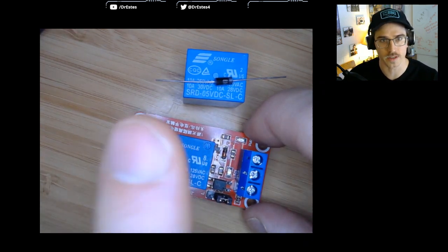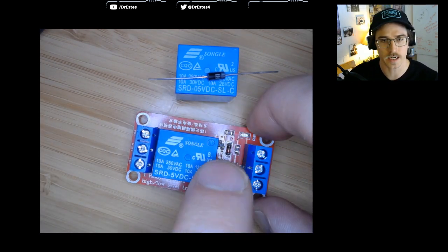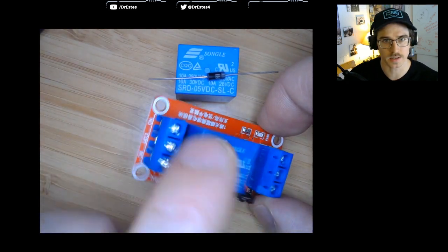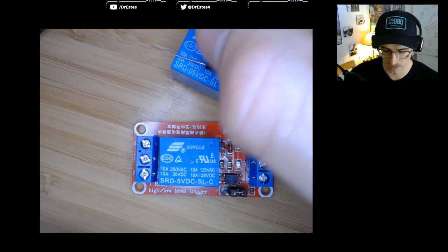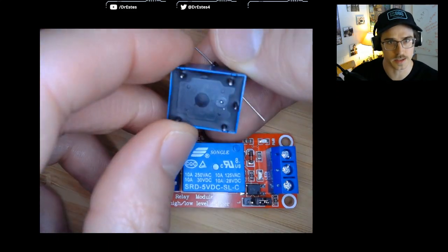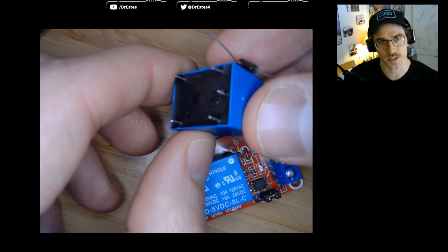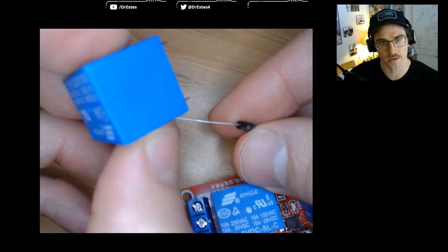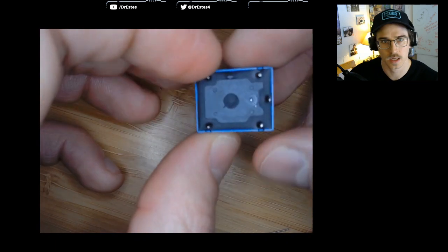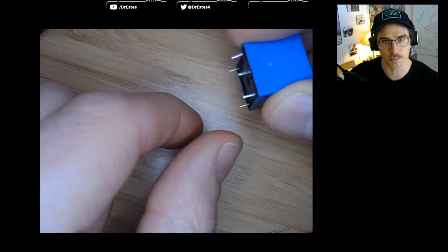So you see it's got the relay on it, but it has this additional circuitry, including a diode, which makes it safe to use and it's easier to connect up some leads. Because if you want to connect stuff to this relay, it has these 5 pins on the bottom, which you can either solder to or try to plug into a breadboard. But the problem is the spacing of these pins is such that they don't fit nicely into the breadboard.